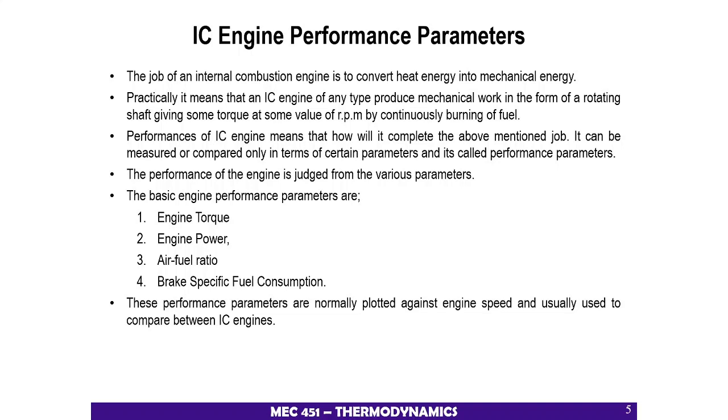The basic engine performance parameters are torque, engine power, air fuel ratio, and lastly, brake specific fuel consumption, BSFC. These performance parameters are normally plotted against engine speed and usually used to compare between IC engines.